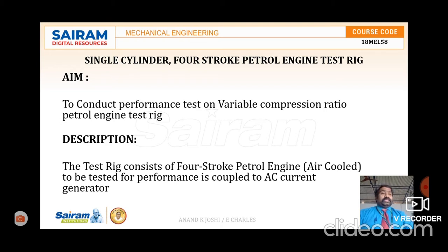electronic digital indicator. The temperature at the air inlet and engine exhaust, the engine water inlet and outlet temperature, and the calorimeter inlet and outlet temperature are measured by an electronic digital temperature indicator, which is connected to thermocouples. Through the sensor we can read those readings, and water flow can be measured by the water flow meter, or we call it a rotameter. The whole instrument is mounted on one self-contained unit for the operations.